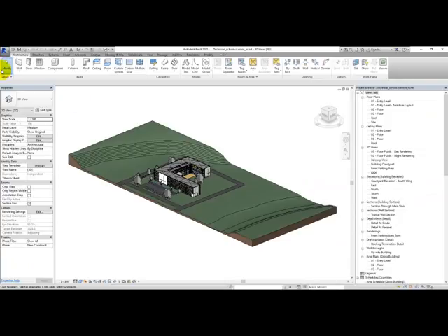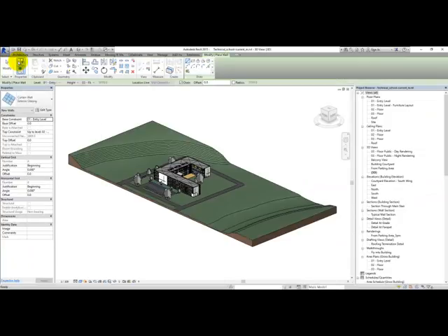By that I mean if I went to wall and clicked on wall, the ribbon changes, and you see it goes this green in the background. They call that the contextual tab. So that's changed that tab, and that tab appears there. That's that green one. We had all these tabs before. When I've selected wall, that tab's appeared, the Place Wall tab. And then all the tools that I need to draw or model a wall are there. That's essentially how the ribbon works.